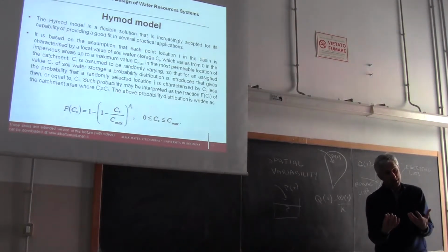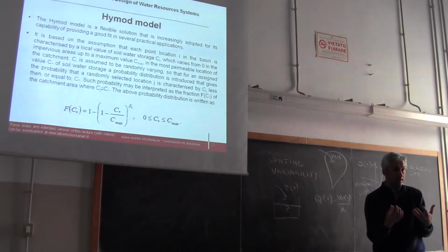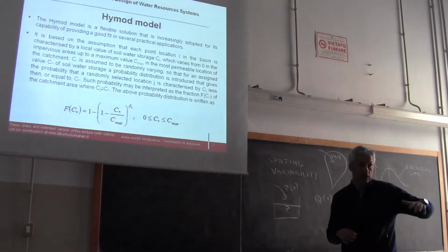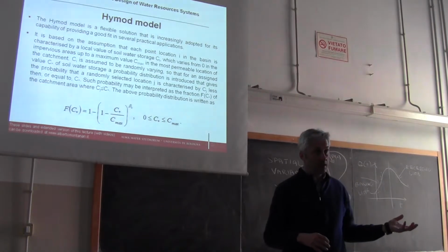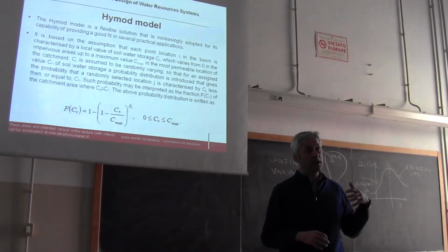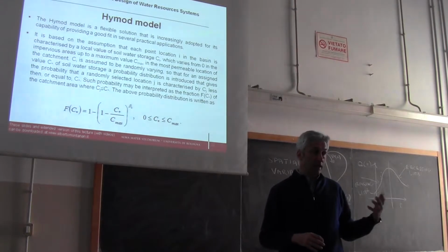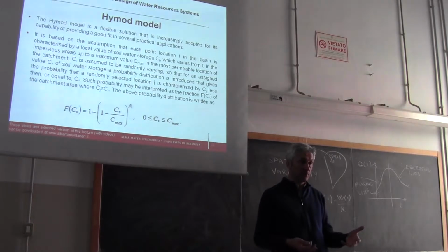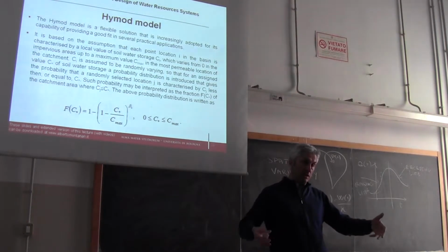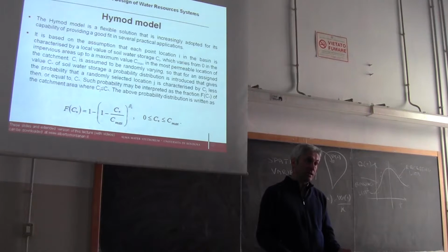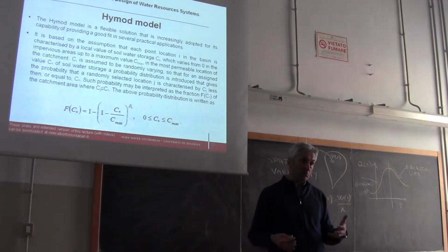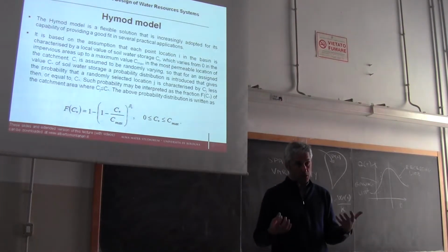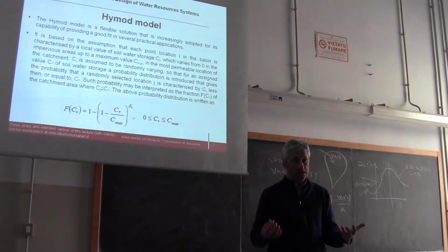If you have areas that are completely saturated, everything that rains over there flows over the ground and doesn't infiltrate. And these processes are spatially variable, because while it rains, you get areas that are easily saturated, like close to rivers. In the bottom of valleys, you have more water available because you are close to the river, so the soil gets more easily saturated.